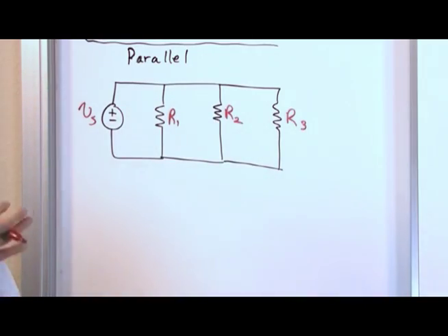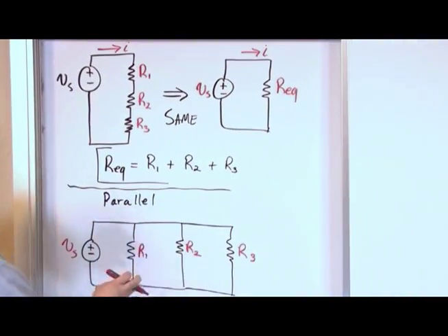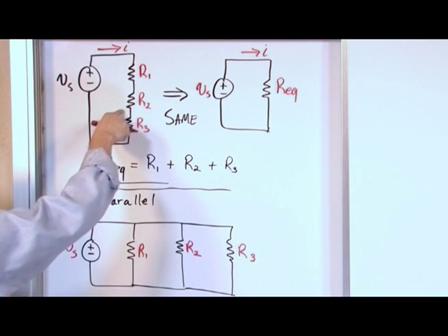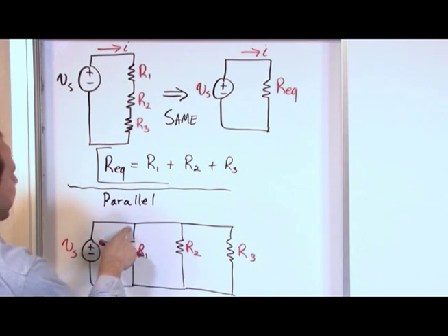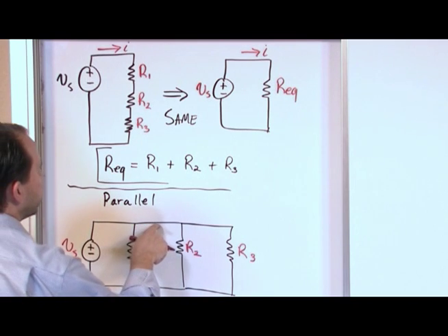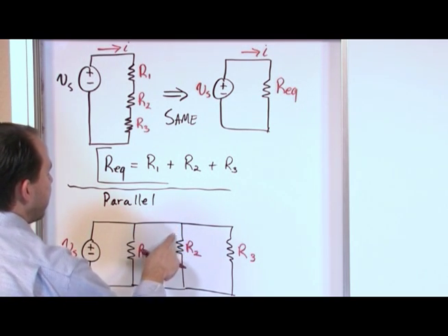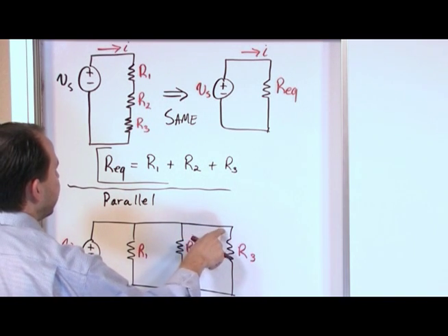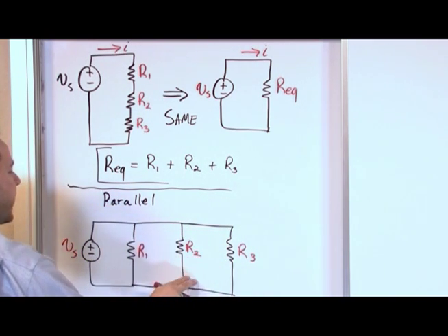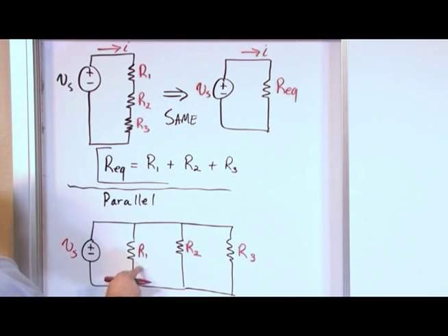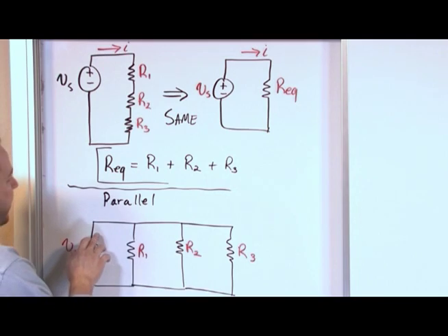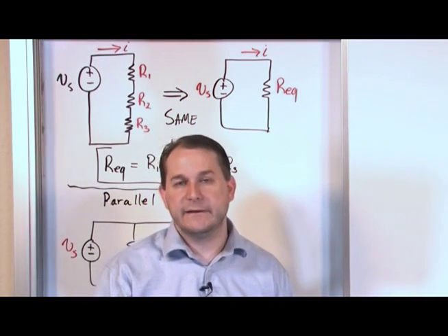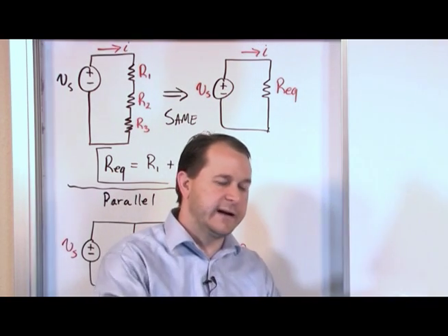All right, so this is parallel. You really need to make sure you understand the difference more than anything. Series is when the current flows through all of the components in series. That's why it's called that. Parallel means that the current's going to come out of the source, some of it's going to split down here, the remainder of the current's going to go this way until it hits this node, and then some of it's going to split here. The remainder of the current's going to go down here, and it's going to recombine with this current, forming this guy, and then recombine with what came down here, and then go back to the source. So this is what we call in parallel, and you can see the difference because in parallel the current branches. That's really the main deal. The current branches because you're hitting these legs and going down there.